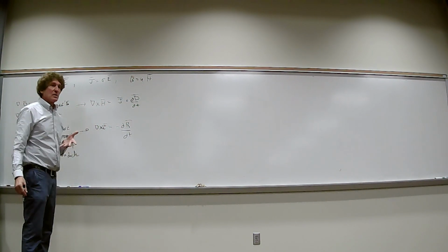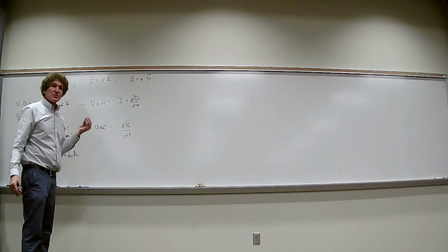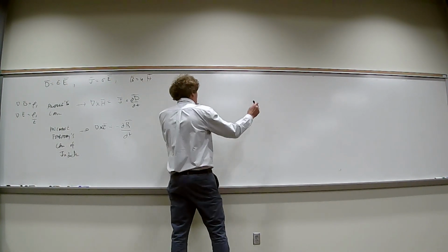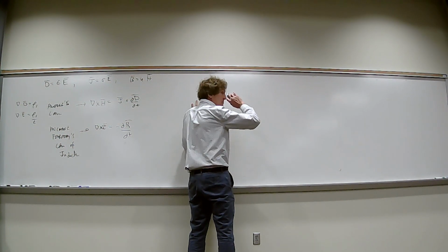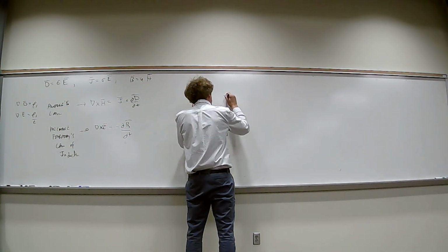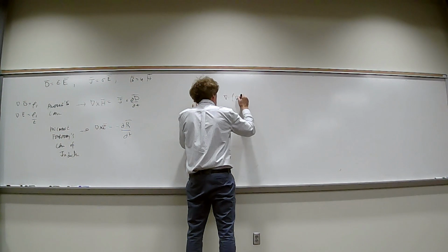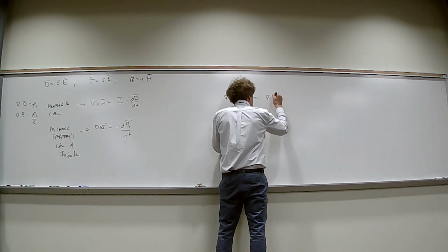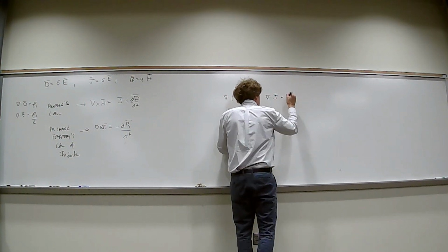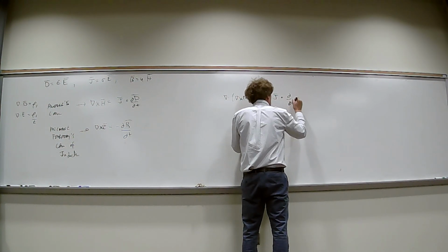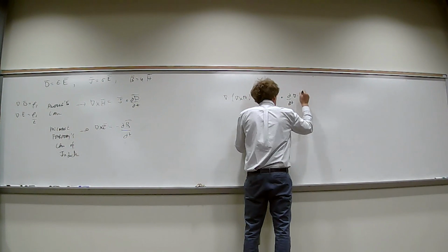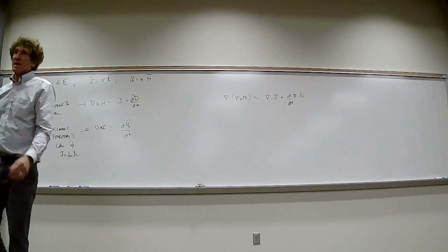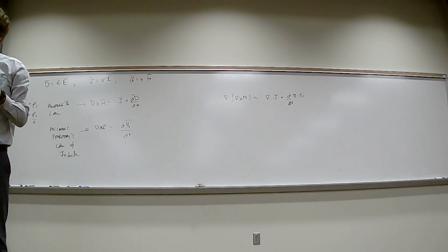It's great to write it down, but what does it mean? So we think about charge decay first, and we do this. If I have the curl of H, that equation right there, I take a divergence of both sides. I take divergence of curl of H equal to divergence of J plus d dt divergence of D. Now just take a look. The only thing I've done is take both sides of that equation and apply the divergence operator. Are you with me, class?